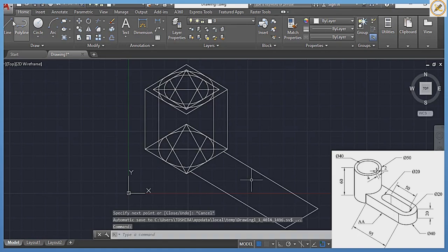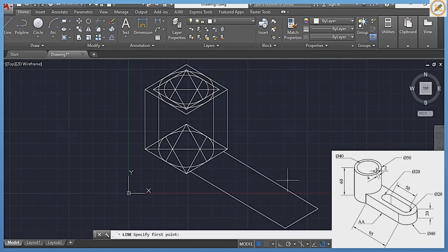So I'm going to pick my line. I'm going to switch on my auto mode. From this area, the height there is 20, enter. Picking my line also, standing right here, the height there is 20, enter. Let me switch off my auto mode.